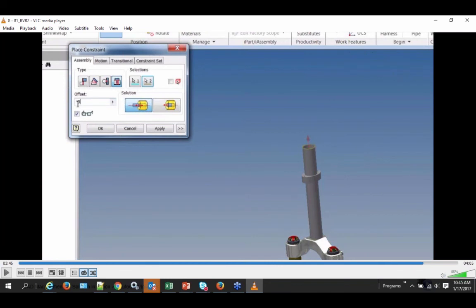So the important point here is that I can make changes not only from the CAD system that will get reflected in the Teamcenter BOM side, I can even make changes from the BOM side. For something like a top-down design concept, where product managers or somebody else who really don't want to work with CAD can go and make some BOM changes, and the CAD designer can then take over. So it gives that kind of flexibility too.